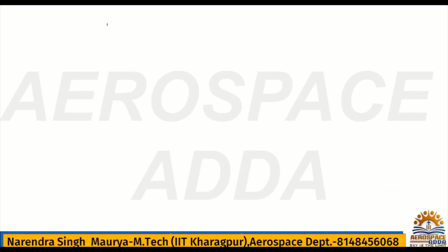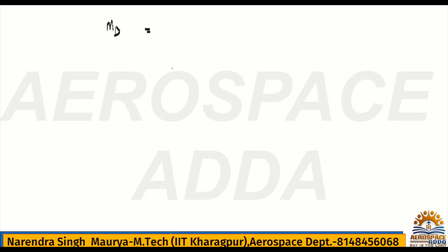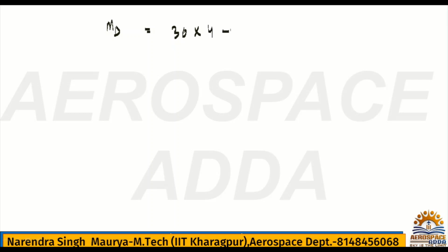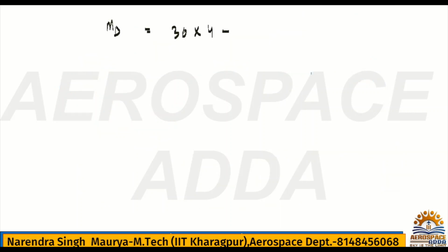Now we'll go for the moment at point D. So if you calculate moment at point D, then again RA and all values you have to write. RA is nothing but 30, into what is the total distance? 1 plus 1 is 2 meter, plus 1 is 3, plus 1 is 4 meter, right? I'll tell you in both ways. So for RA, total distance from D is nothing but 4 meter.